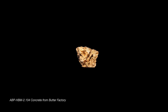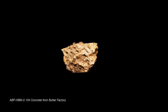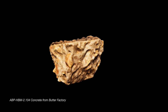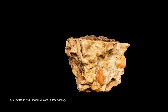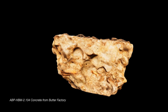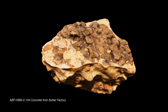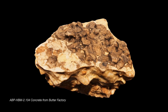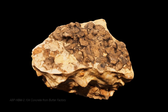Now here's an example of a primitive form of concrete, quite strong. It's from a butter factory in Gippsland, and you can see in here all the local pebbles, some river-worn pebbles, local materials. Smooth pebbles are not desirable for concrete. It's better to have sharp, broken stone than these smooth ones, but this is nevertheless pretty strong. In this case though, an unusual detail here, on this side, what appears to be some sort of burnt cork material. And this is because it was a butter factory, and this was the insulation in the walls of the factory.